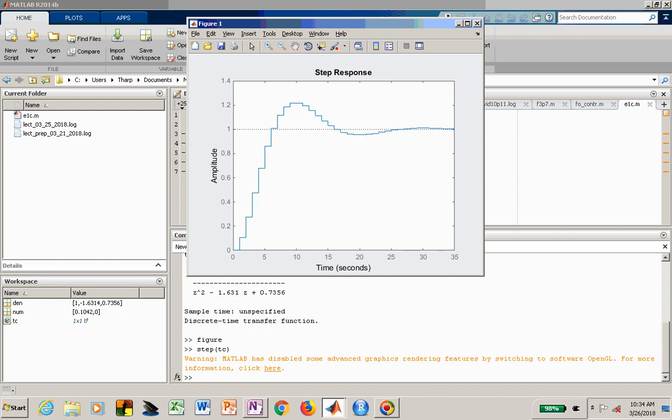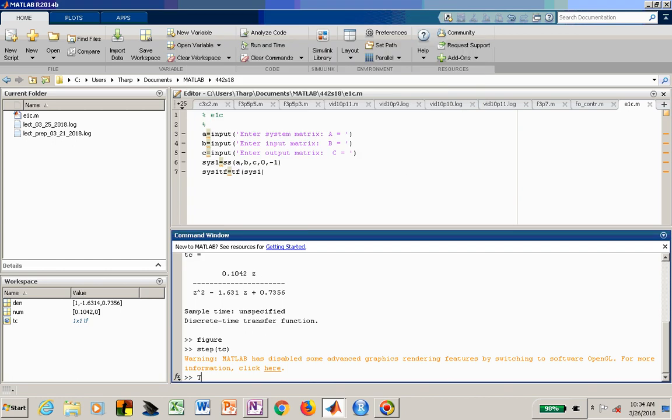So let's make MATLAB a little bit more honest with what it's saying is the horizontal axis, by specifying a particular sample period. Let's introduce the sample period we had experimented with before in our aside comment, which was 20 milliseconds, or 0.02.